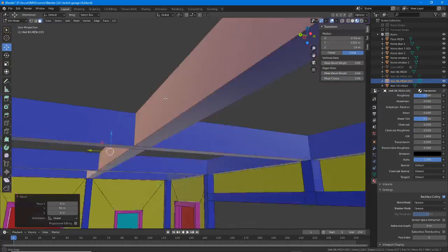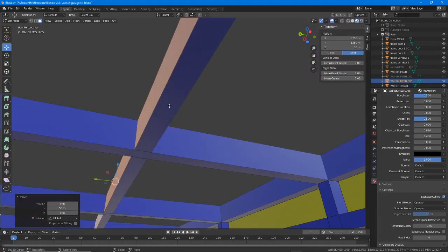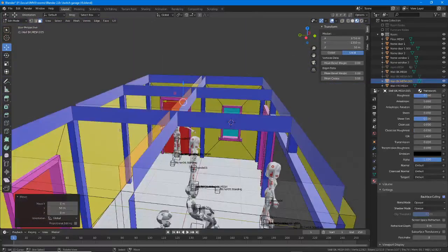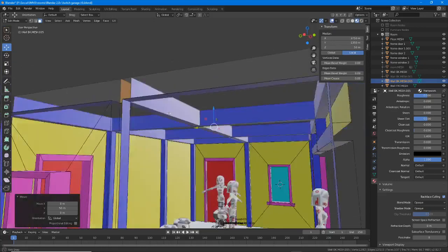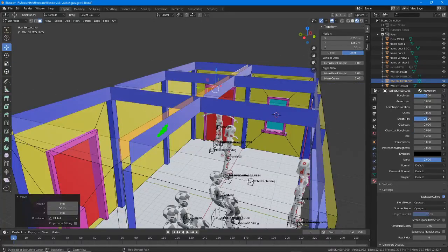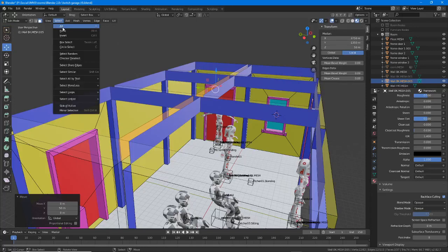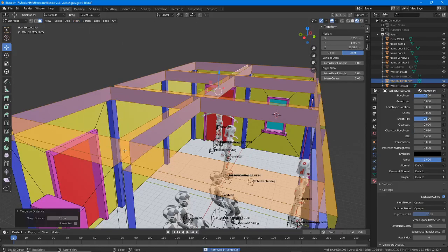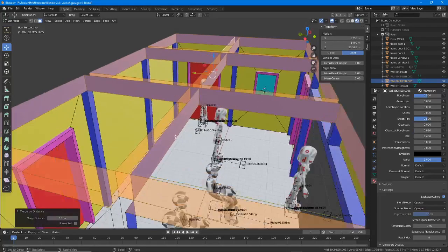And the reason for doing that is so that we don't waste too much time inverting and reverting and changing and flipping around the surfaces. So basically this side can be a copy of this, and this side can be a copy of this, and then all we do is just select all, mesh, clean up, merge by distance, and we remove the additional vertices that we've created. But what we also need to do,